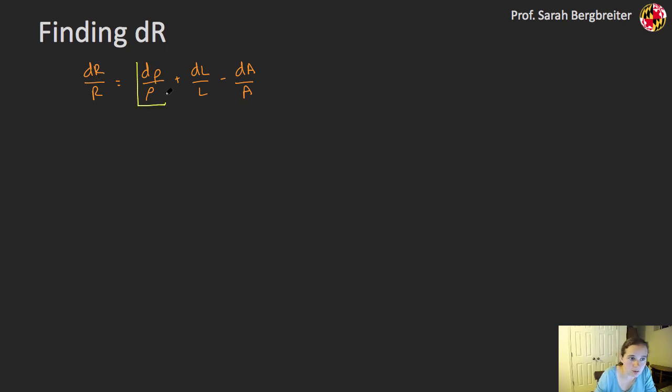This d rho over rho term is going to be based on any piezoresistivity I might have in my sensor. Right? The dL over L term, that's effectively my strain that I'm looking at, right? So I'm just going to write this as my strain. In this case, I'm going to assume an axial strain. And then I have this dA over A term.